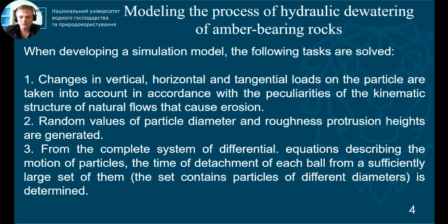During the development of a simulation model, the following tasks are solved. Changes in vertical, horizontal, and tangential loads on the particle are taken into account in accordance with the peculiarities of the kinematic structure of the flows that cause erosion. Random values of particle diameters and roughness protrusion height are generated. From the complete system of differential equations describing the motion of particles, the time of detachment of each ball from a sufficiently large set of them is determined.